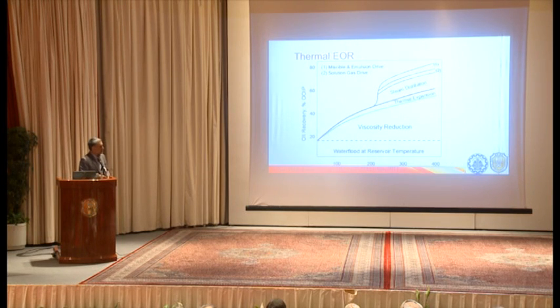Okay, so this shows the mechanisms behind the thermal EOR. For thermal, whatever we do with the reservoir to increase the temperature, it appears in the viscosity reduction, changing the viscosity from high value to low value, or thermal expansion, or steam distillation, or other mechanisms. Okay. So we would like to increase the temperature of the reservoir. What do we face in the reservoir? We have rock over there. And the pores, and the fluids are inside those pores, okay?